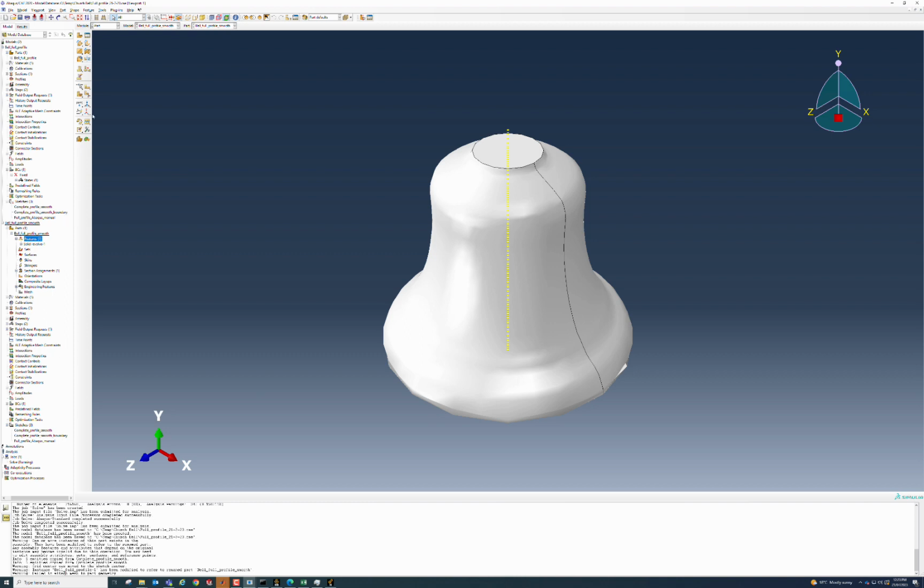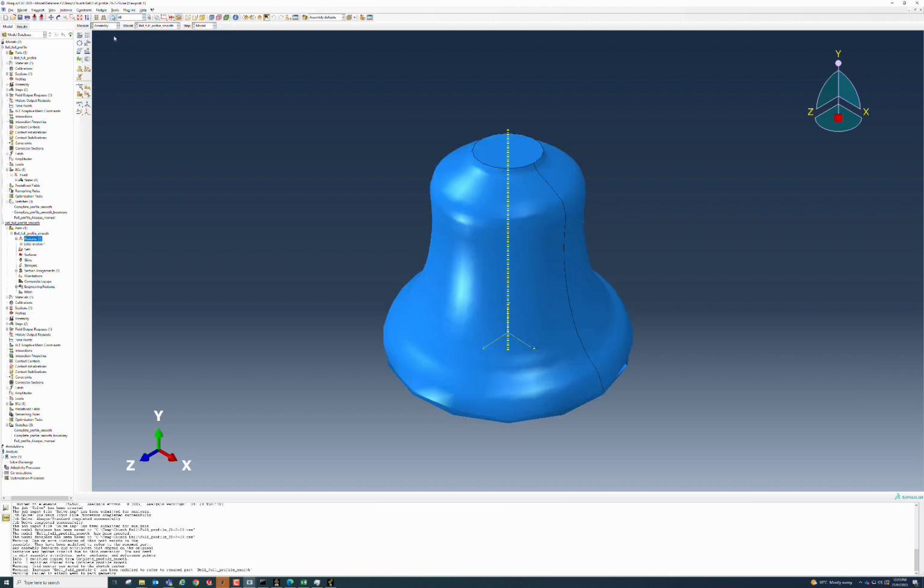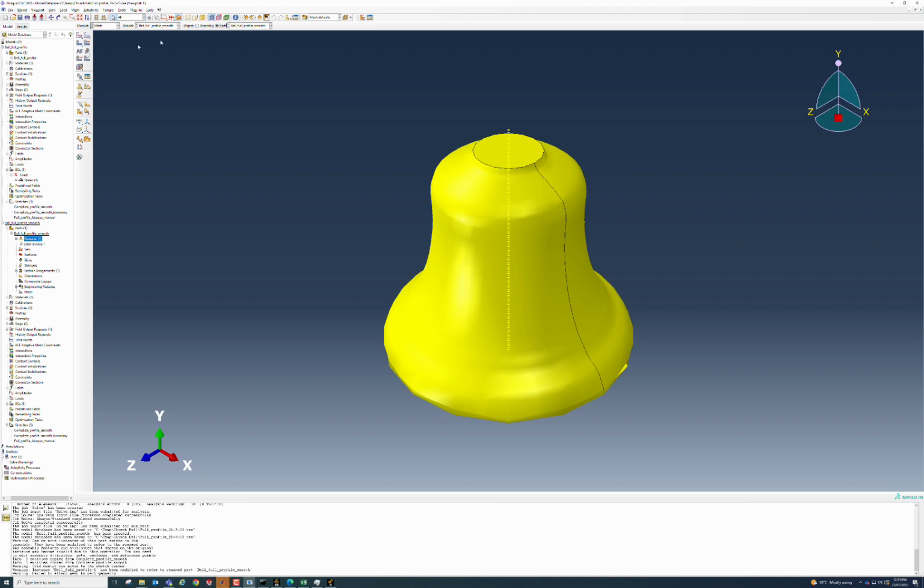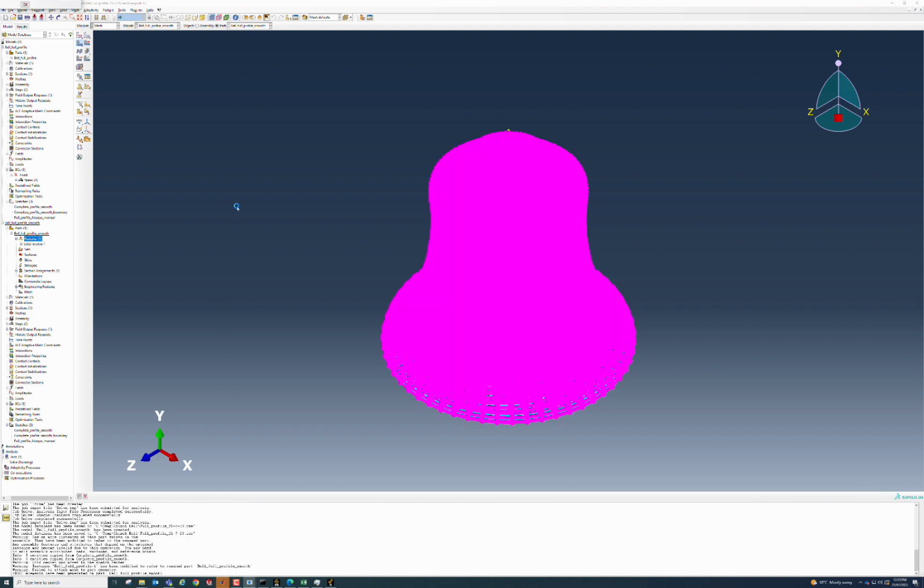At this moment we have a look at the assembly, it's also regenerated there, and we can go back to the mesh functions and apply some seeds. Remember, it's a dependent part instance. Change the seed size, run the mesh, and it takes a while. Remember, we're still running the solution at the same time on this machine presently, and you can see immediately there are lots of errors now with our mesh, which we need to resolve.